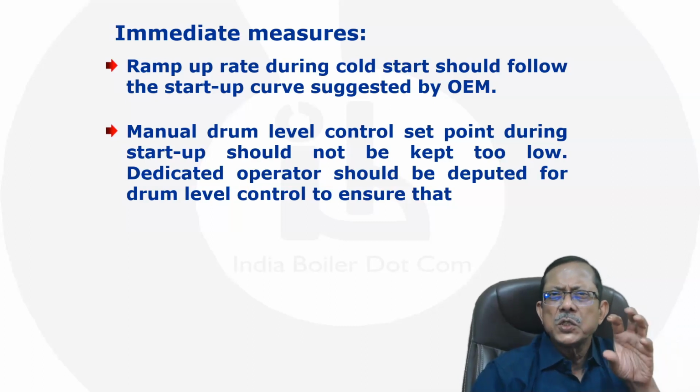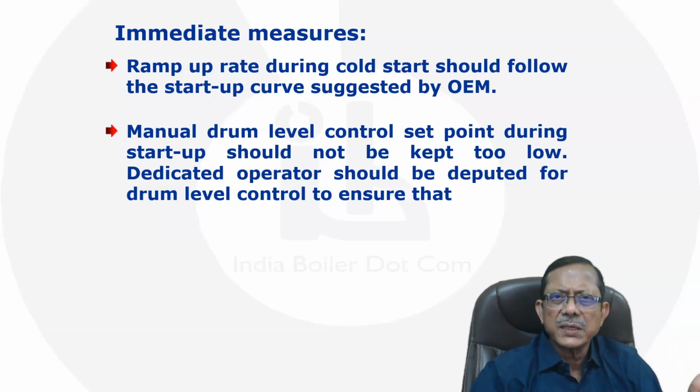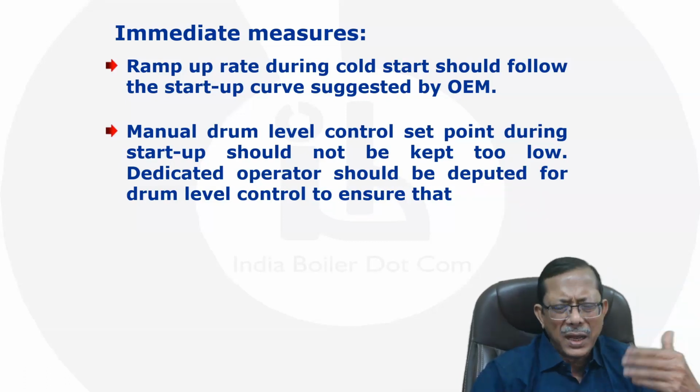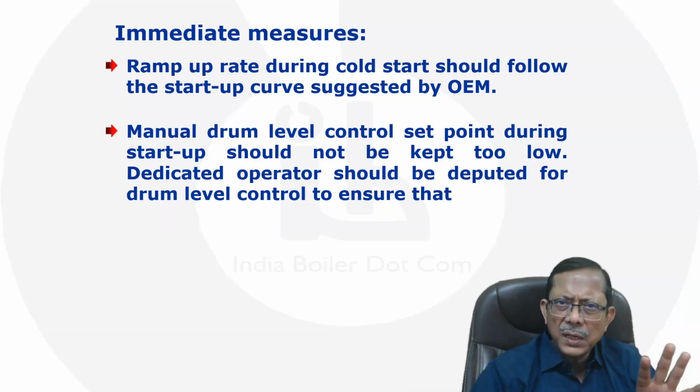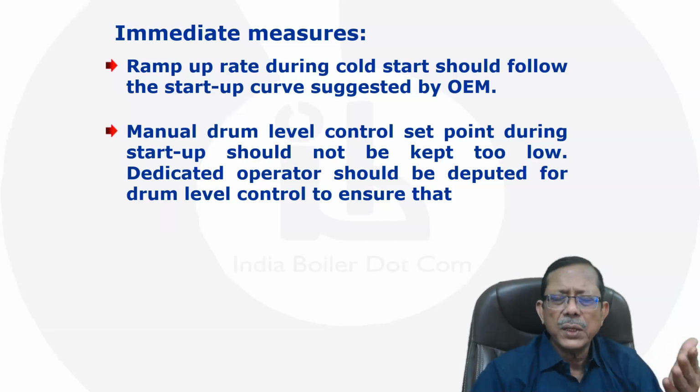The second thing is that they have to have very thorough, very strict level control during the cold start, because at that time it is a manual control, right? And because of the swelling phenomenon they have a tendency of keeping the set point level a little low at the time of cold start. In one of my videos on circulation I have explained what harm that can lead to, right? So they have to have a dedicated person for the level control during the cold start. That is another suggestion to them.